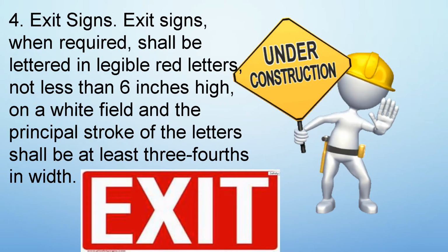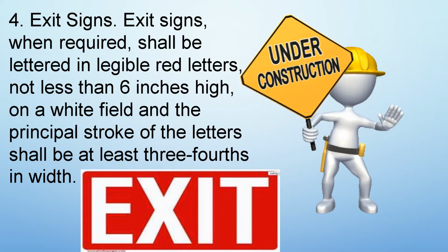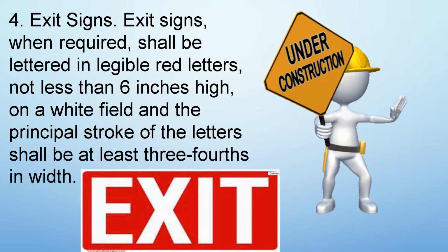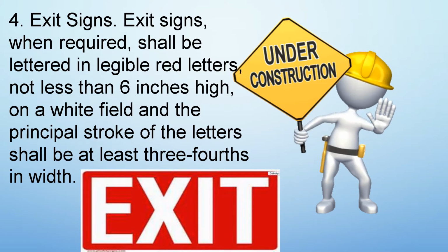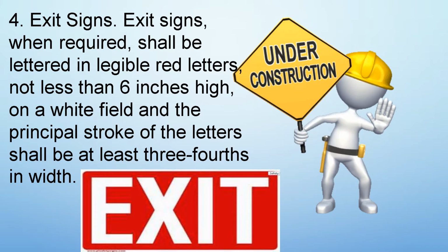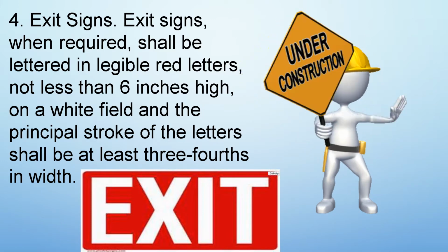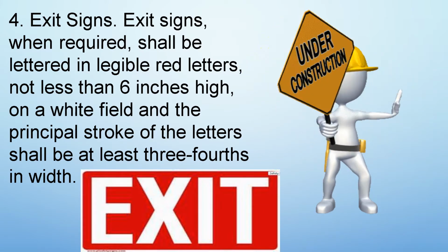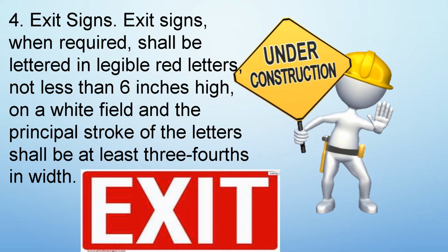Number 4. Exit sign. Exit signs, when required, shall be lettered in legible red letters, not less than 6 inches high, on a white field, and the principal stroke of the letter shall be at least 3/4 inch in width. So, as you can see in the picture below, that is the example of an exit sign.